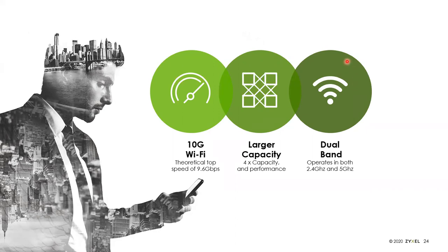Another key thing to keep an eye out for is that not every vendor selling a Wi-Fi 6 product has actually bothered to put Wi-Fi 6 on the 2.4 radio. So we just had that question about Ubiquiti. Ubiquiti's Wi-Fi 6 products only have Wi-Fi 6 on the 5 gigahertz radio. The 2.4 radio is still using that 10-year-old 11N technology on their so-called Wi-Fi 6 AP. So that's something to keep in mind when you're comparing: verify that it's truly Wi-Fi 6 on both radios, not just half.